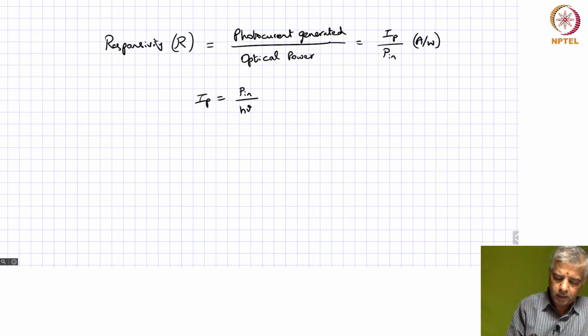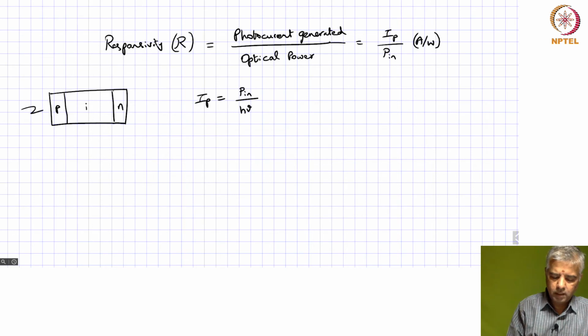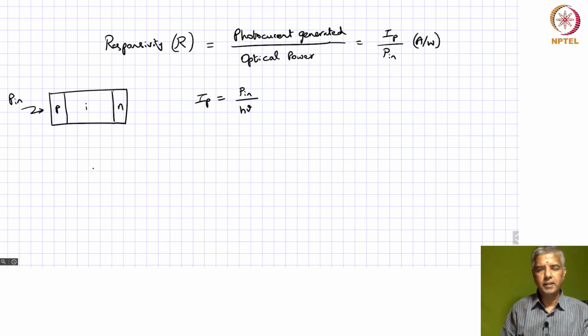If you look at, let me just draw this PIN structure again. If you look at light that's incident on this structure, not all the light that's coming in, so this corresponds to P, actually goes into the structure, because this material is typically like indium gallium arsenide, let's say, which has a refractive index greater than 3, and outside you have air which is refractive index of 1.